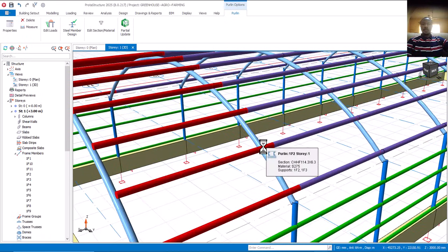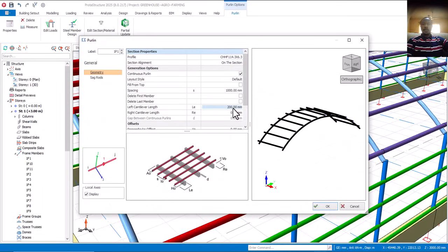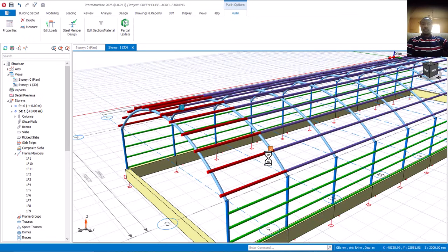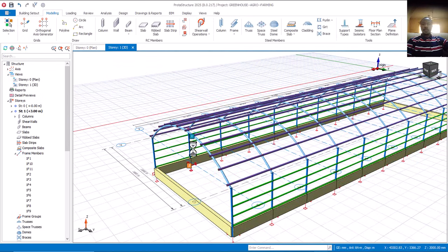Okay, no, can you see it has projected this side? So this is not what we want. So I'll right click again, property. I'll go to that place now. This one, turn to 0, then come to the second one and make it 200. Is that okay? Click somewhere else and then click on OK. So can you see what we have now? As simple as this.